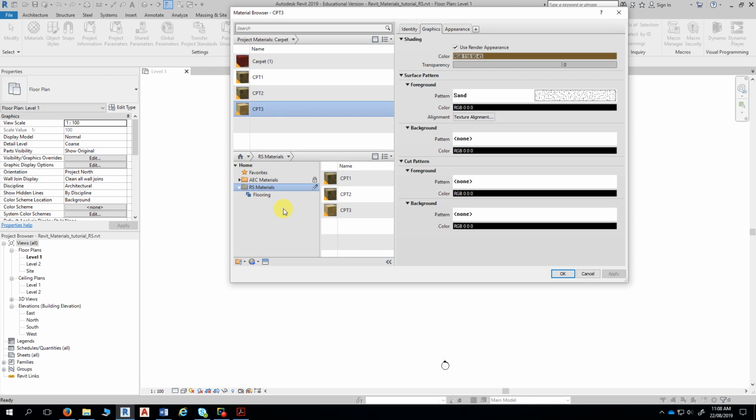So if you're going to work on this at home, you'll have to link the library to your Revit installation at home. So if I right mouse click on the library here and say remove library, it then removes it from my Revit installation on this computer. Now, let's say I'm going to another location with another Revit installation.